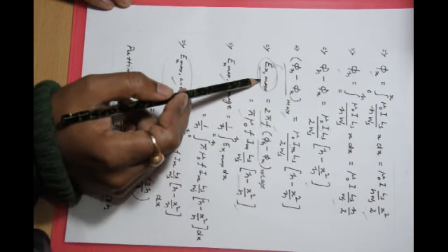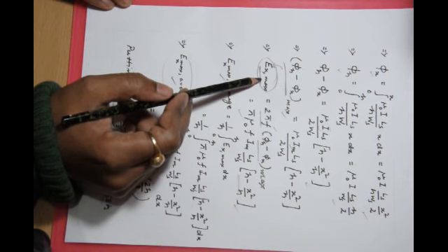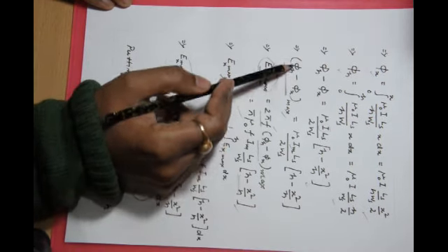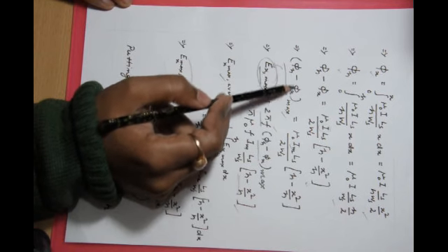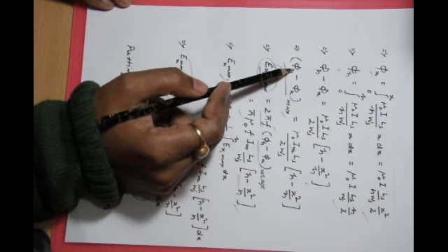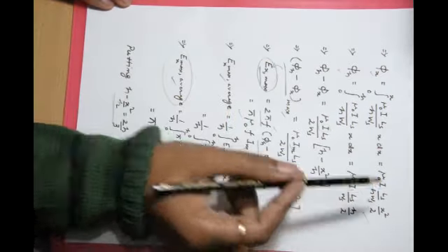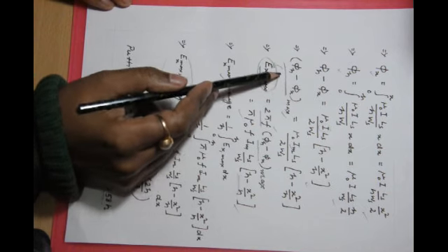What is Ex max? Ex max is the EMF induced in the element, and it is in quadrature with phi h minus phi x. See, phi h and phi x are in phase because they are formed by the same current, but Ex max is in quadrature with phi h minus phi x.